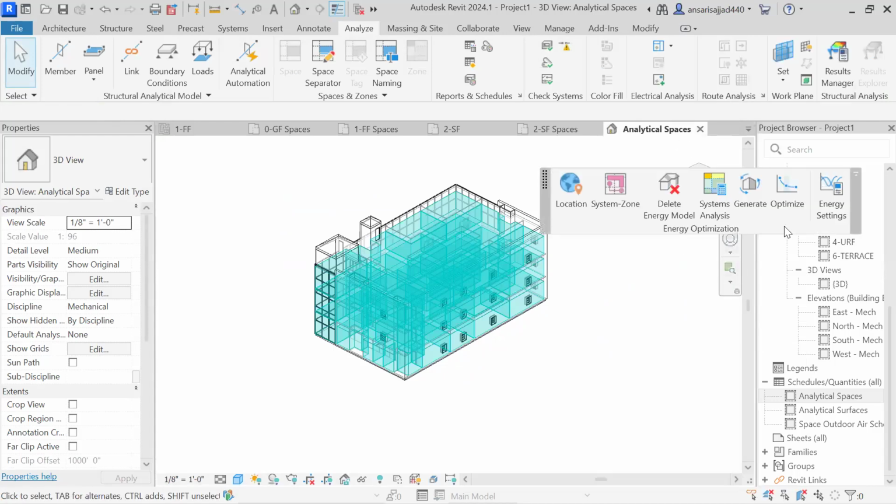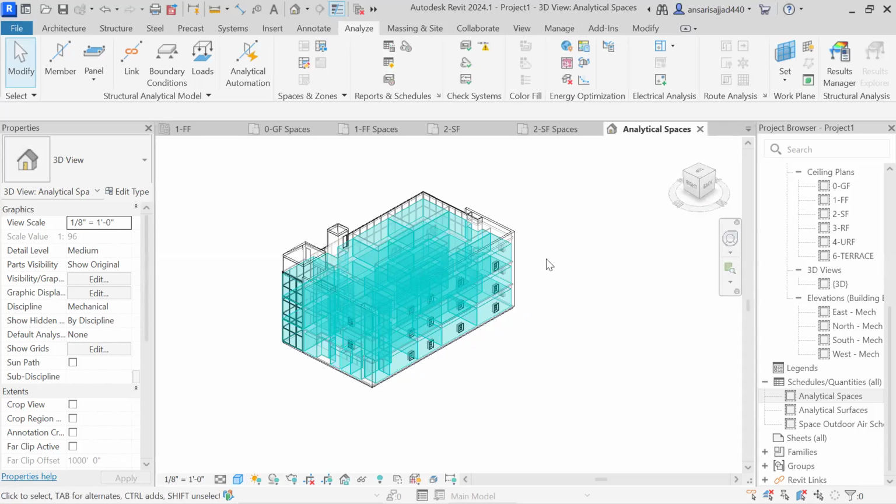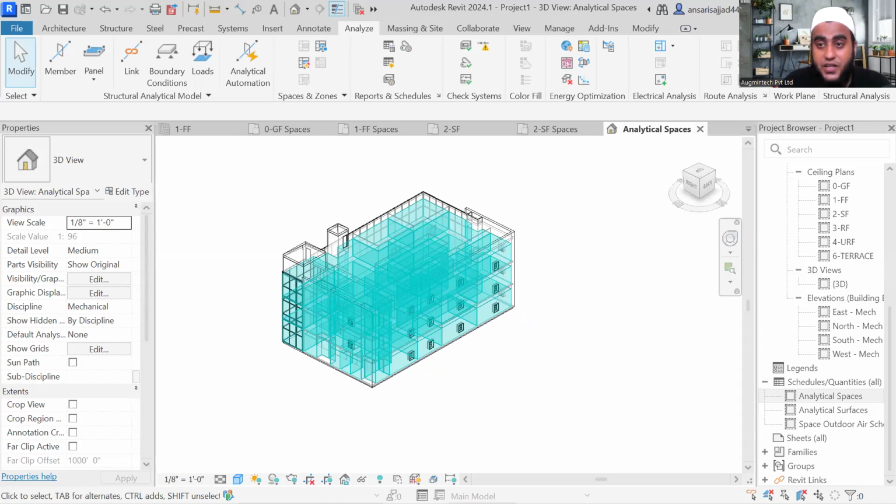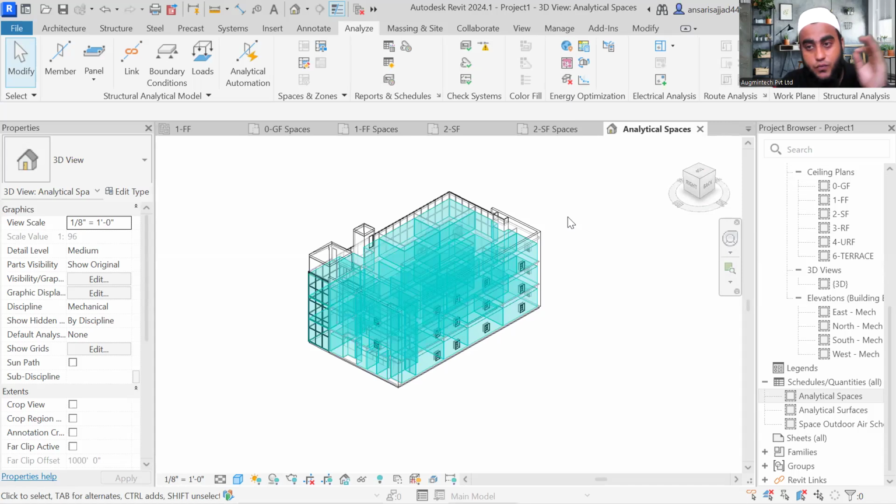So now what I'm doing, just take it and place it here. Okay. So after that, the next step is what? Now we have to add the water loop, air loops, and zone equipment. This is a very important step. All of you listen carefully. Whatever step I'm teaching here, please listen carefully. Each and every step is very important. Okay. So see, now the important thing is what? We have to add the water loop. Means which type of system you are using, chiller or what? How will Revit identify? You are supplying air conditioning with the help of chilled water, direct expansion system, or what? All detail we have to see.